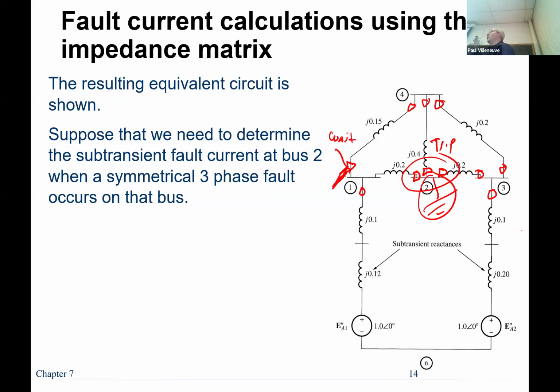Well, energization of a load, there was enough load through it. And it tripped on differential, which usually means there's a problem inside the generator. And the guy calls me up and said, hey, it just tripped on differential when we bumped the motor, but we don't have power at the site. Can we turn it on? Can we energize the transformer? And I'm like, boy, that's a dangerous thing. When the transformer's got a failure inside, you're going to hit it again, more damage is going to occur.